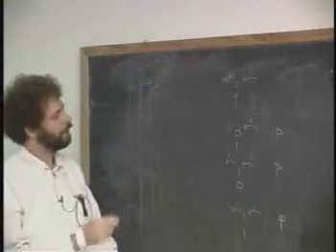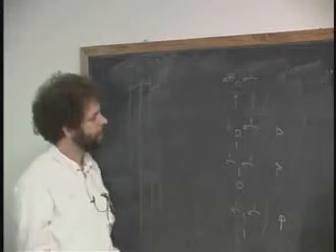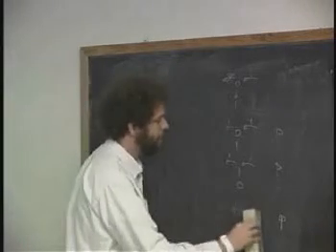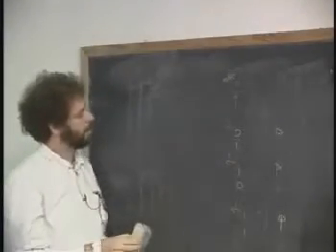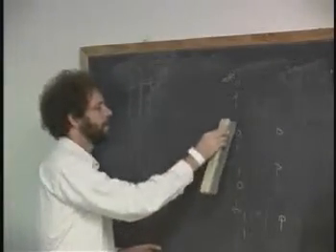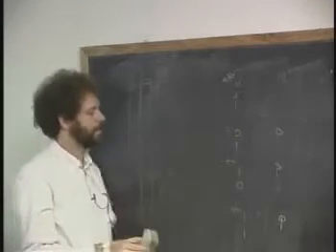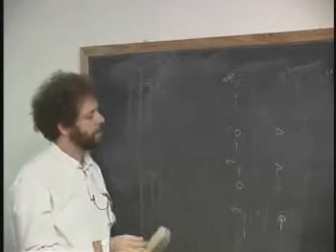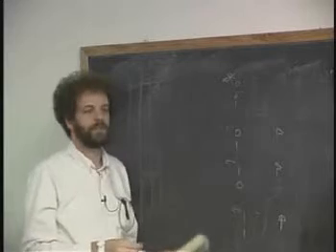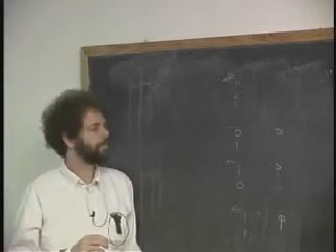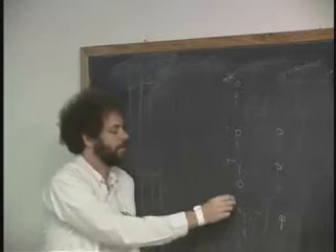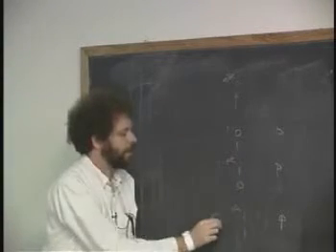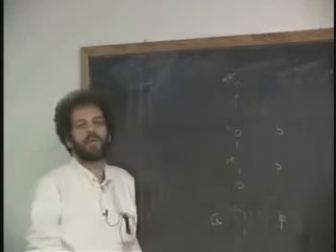Okay. Second question. Independent of what the carry-in is, let's say I don't worry about that. I only worry about these bits here. Assuming that the propagation is handled in a separate way, in which cases here do I generate a carry, irrespective of what comes in? Here, no. Here, no. Here, no. Here, yes. So here I generate, and in those three cases I propagate.